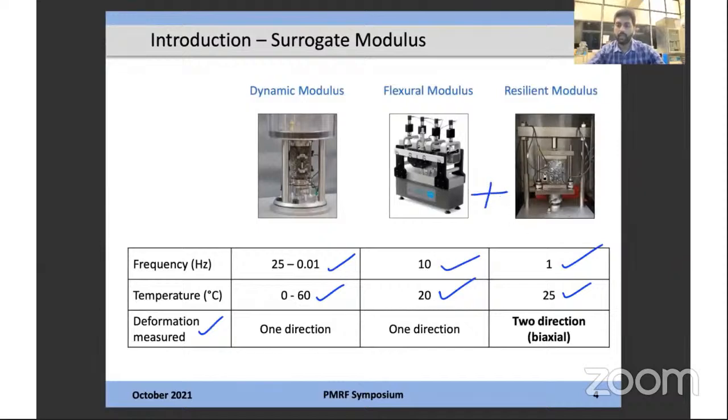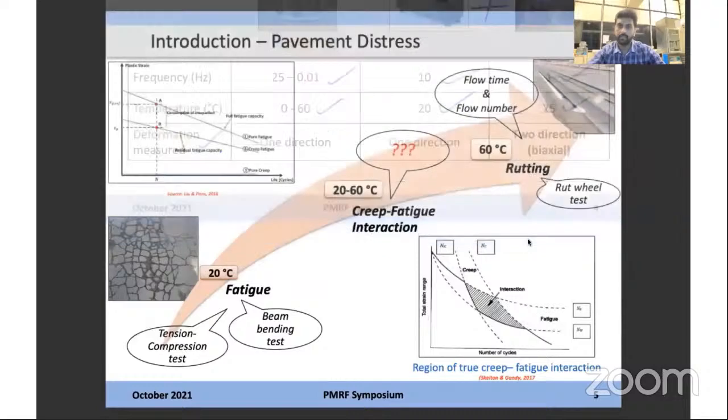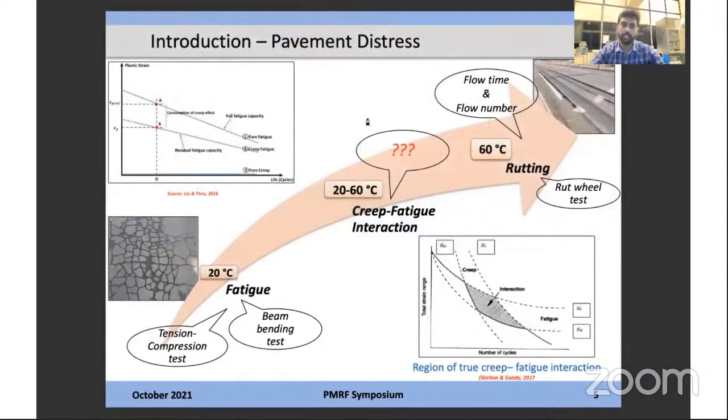One interesting fact to be noticed is that the deformations were captured not only on one face of the sample, but also on the opposite face of the sample. So the ITT mode of test, which is preferred for resilient modulus estimation, gives a better deformation or response of the material for further investigation.